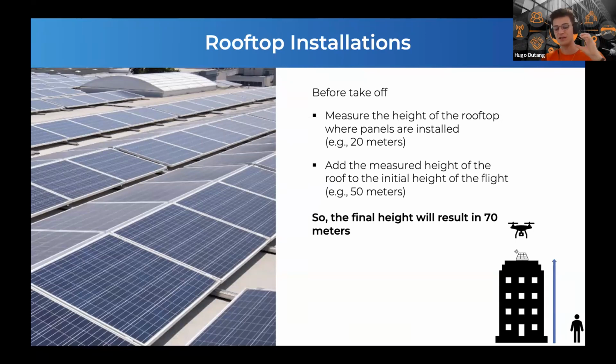This is done automatically by the application once you fill in this blank field. At the beginning it's blank, and then you put, let's say the building is 10 meters, you put 10 meters in this field, and it automatically calculates the right GSD. It's called surface to takeoff altitude or something like that. Okay. Are you translating it directly from French? Yeah. I did my best, but you'll find out. This is in the flight parameters. Okay, great. That's really good to know.